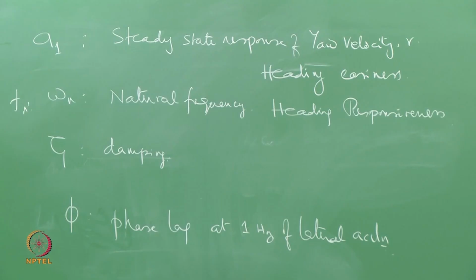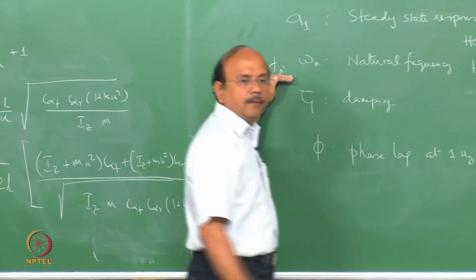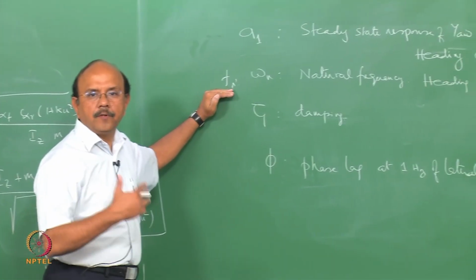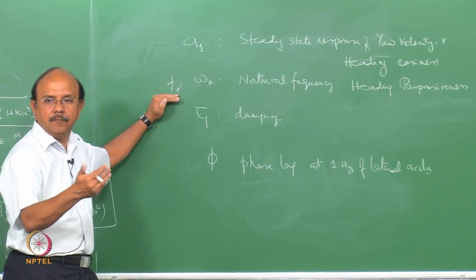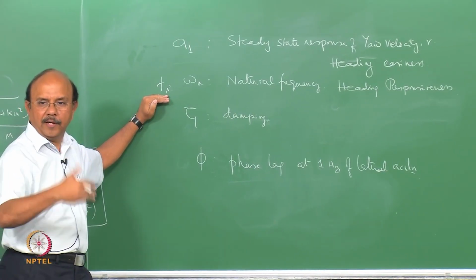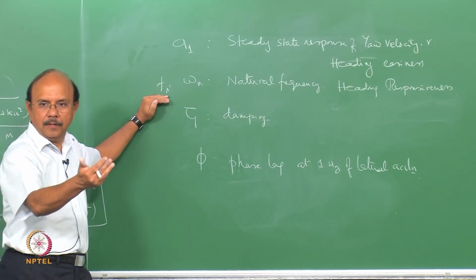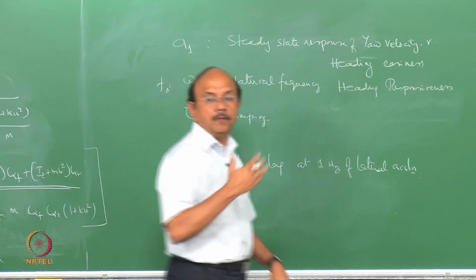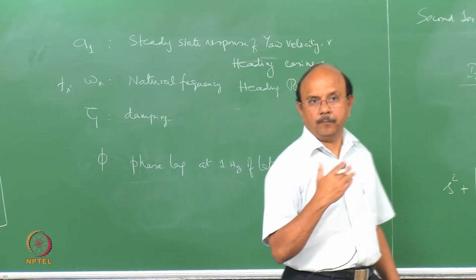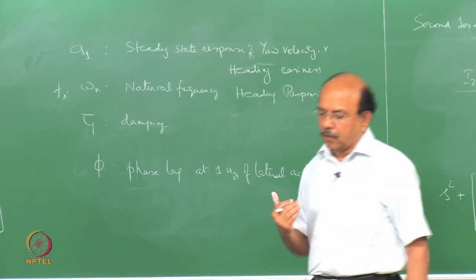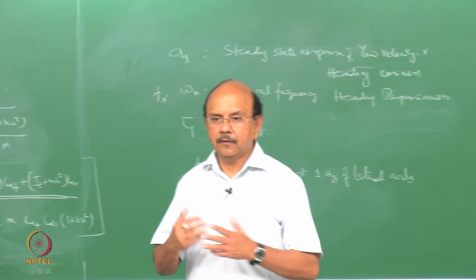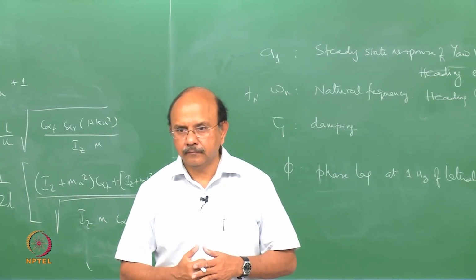So can you please explain this? Yeah, what is the, all the factors like settling time, which is 4 divided by omega n into zeta, and the peak time, all those factors are all functions of omega n.